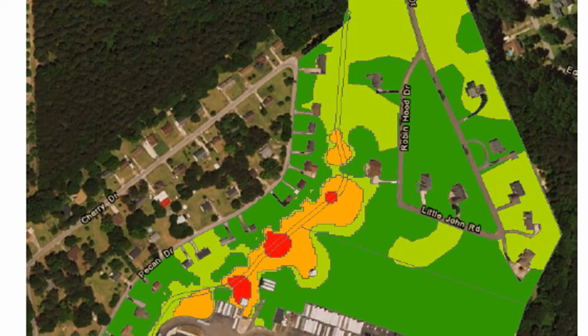At this site, low-density sampling collected through traditional means and sent to a lab for analysis was extrapolated to produce the concentration gradients below. The concentration gradients that are orange and red are the highest concentrations. The contaminant of interest, PCBs, has both relatively high analytical costs and, if determined to meet the regulatory designation of hazardous waste determined by its concentration, it can have disposal costs up to 300% higher than the soil contaminated with lower concentrations.